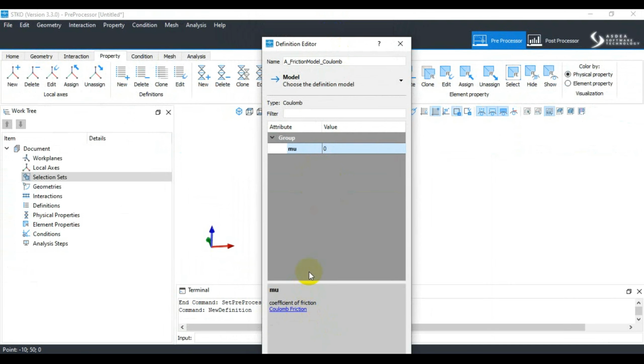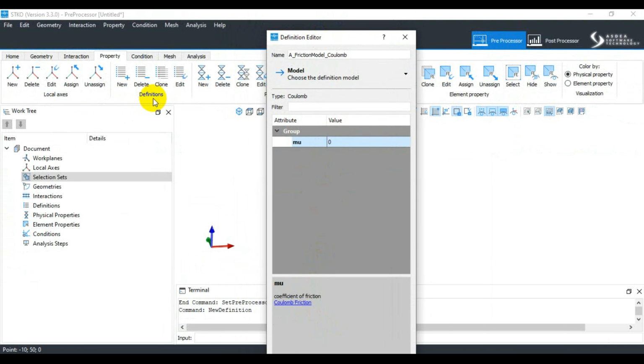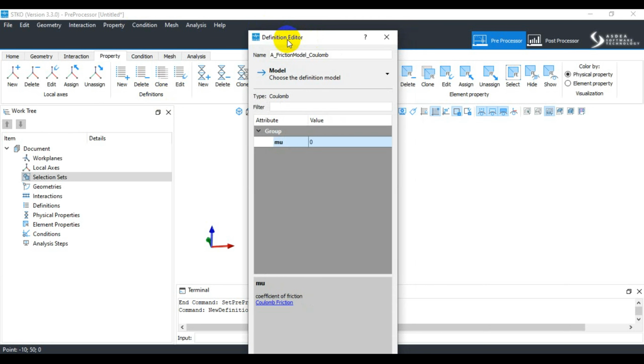This friction Coulomb model is a material model used in OpenSees to simulate friction behavior between surfaces that are in contact with each other. It captures the phenomenon of sticking, meaning no slip until a certain force threshold is reached, followed by sliding with a constant friction resistance. There are some key parameters present in the OpenSees model in the back end of STKO.